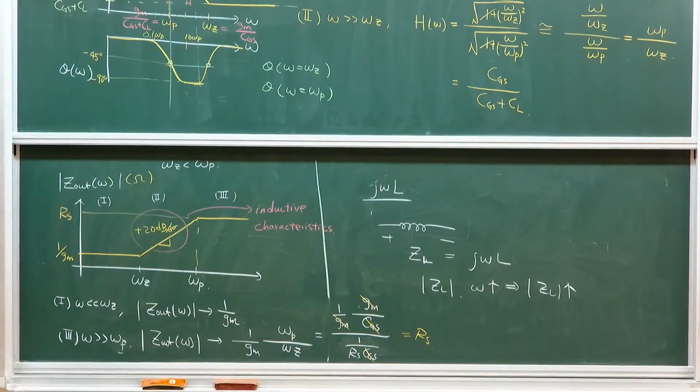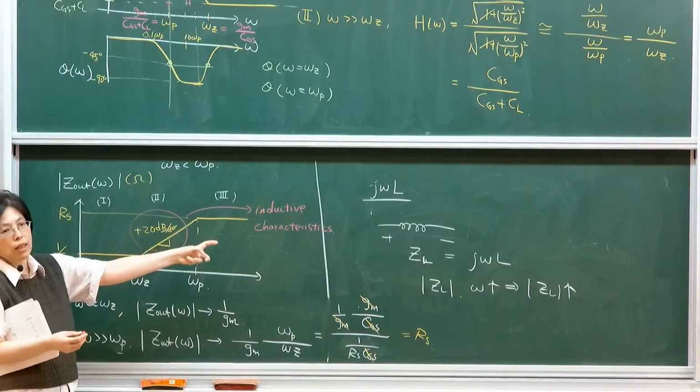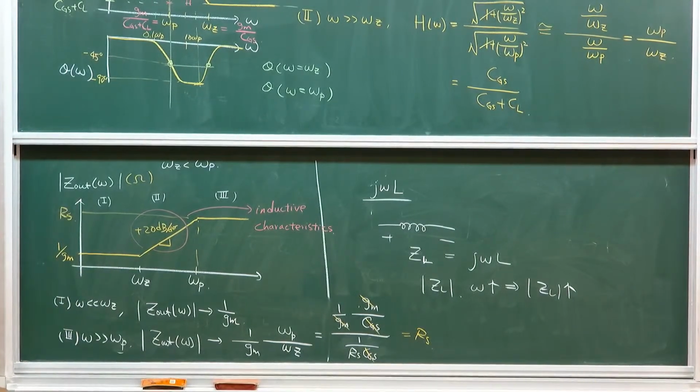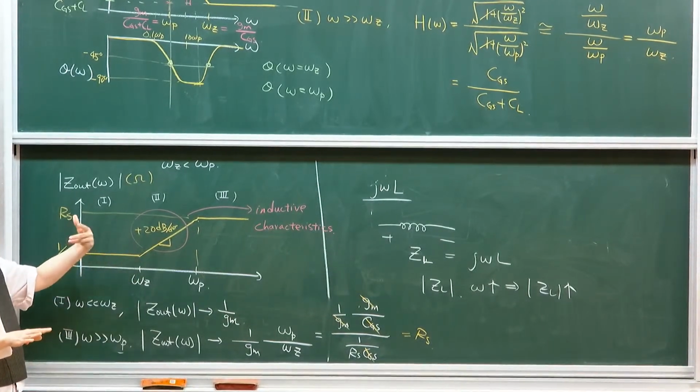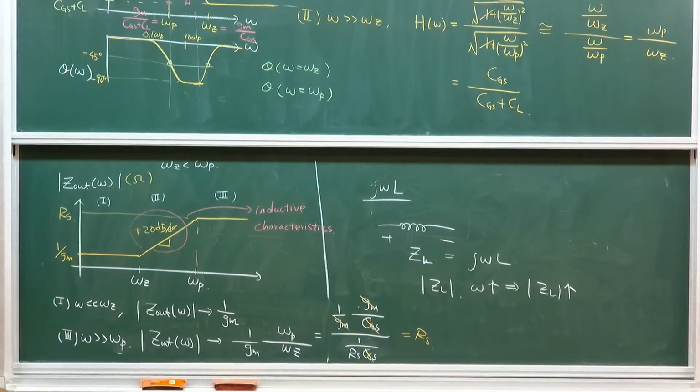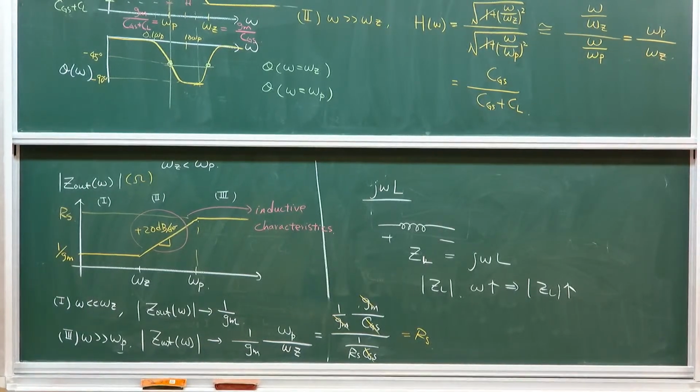In an integrated circuit, there are two ways of realizing an inductor. One is to just build an inductor, but it's very costly and very hard to build inductors. So you can actually use a circuit to simulate inductive characteristics. For example, if you want to build an oscillator, everyone has heard of LC oscillation. You want inductive components and capacitive components. This is the way of creating inductive components using a circuit, using a follower circuit to simulate the effect. Okay? Good?